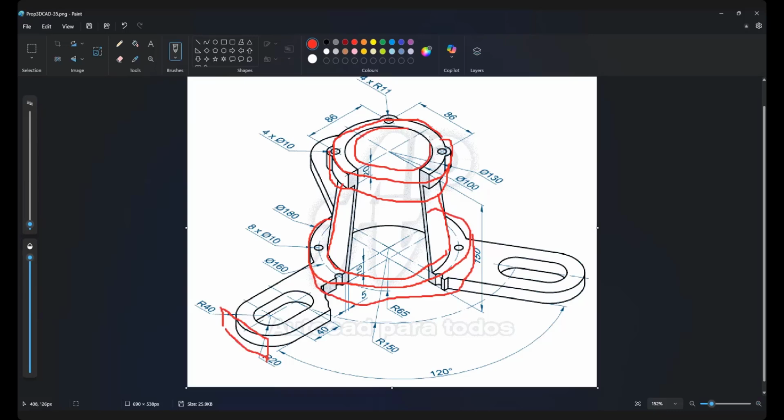First we draw the base profile, just now we revolve, we have this cylindrical shape, this cylindrical object. Then I will draw this rectangle at this plane. So I will do extruded up to surface. I will show you. Extruded stops at that surface. So we have this rectangular block.